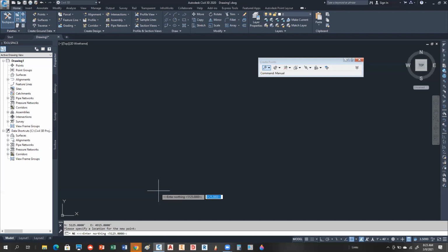So we're going to go ahead and just enter the next one. It should be asking me for a northing. So I'm going to go ahead and type in the northing, 4925, and then hit enter. For the easting, that's going to be 4564, and then hit enter. Point number should be 2. And notice, because we used control last time, C and T, it's already there. So I just hit enter and it's accepted it.